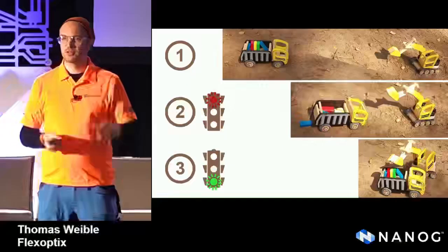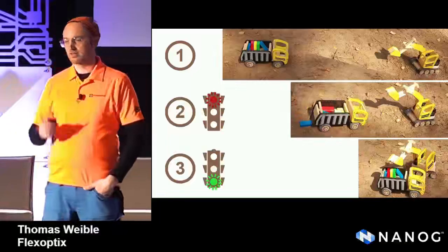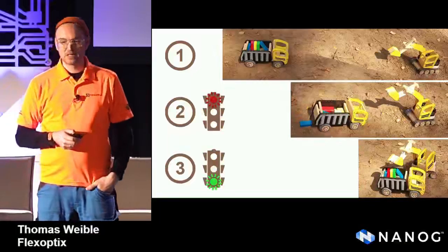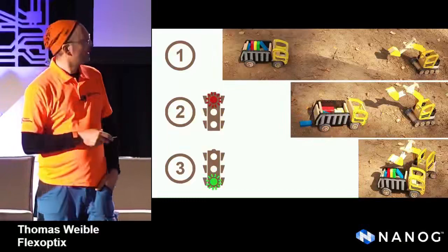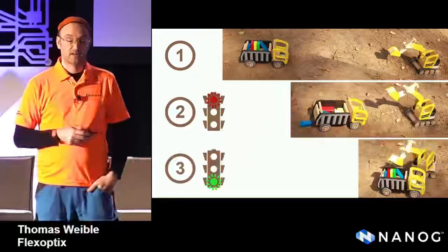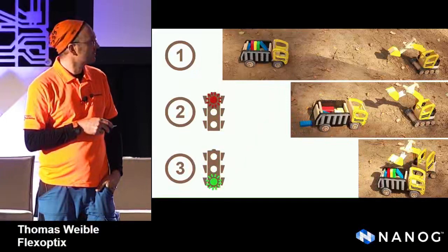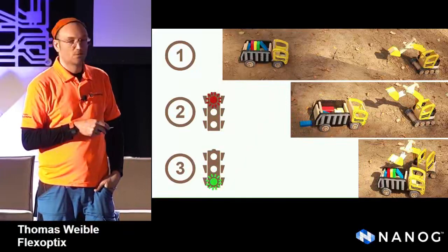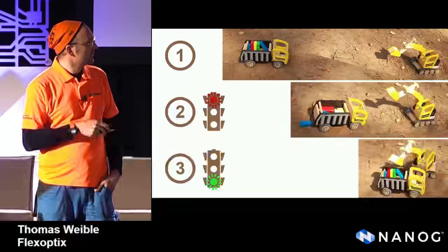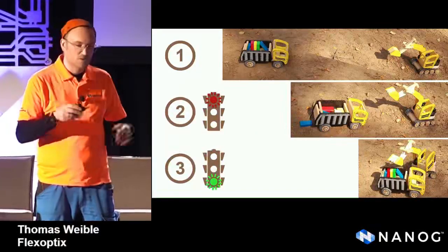I took an artificial example here with a lorry and a truck to explain a little bit. In the first step, the lorry is our FEC encoder, and the bricks on the lorry itself are our payload. And then when the lorry hits the dodgy road, which is our fiber, all the bricks inside get somehow disordered.